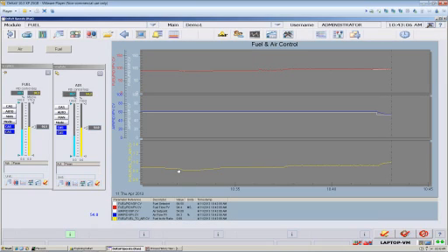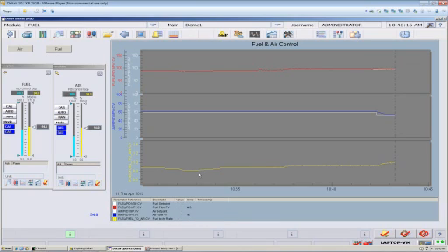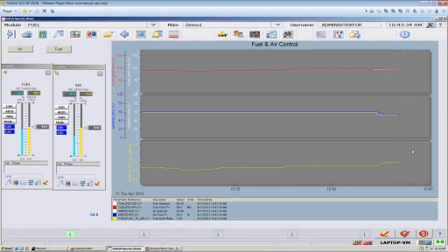this is something in the real world you're going to want to pay attention to. Communicate with the operators, make sure that your bump tests are still within acceptable ranges. You've got to be a lot more careful in a real plant than we were with this simulator here. But make small, reasonable changes. Get permission first. This can be lived with. You just have to know how large of a change you're allowed to make.